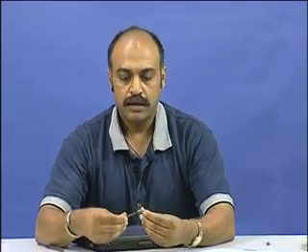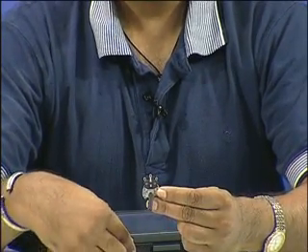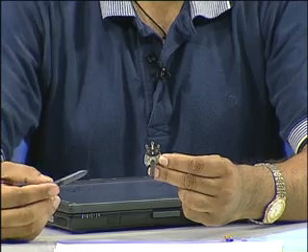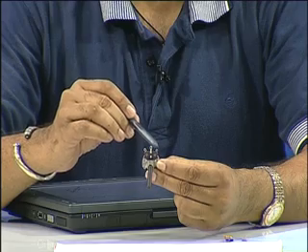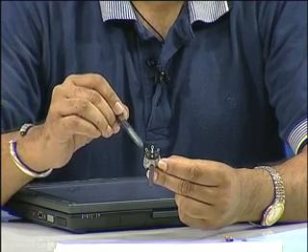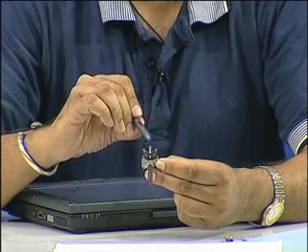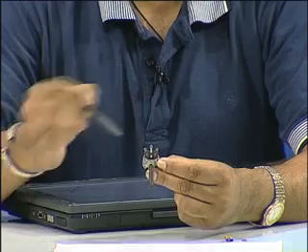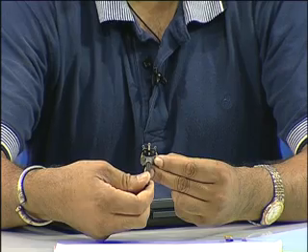Apart from these resistors, there are other resistors which are bigger in size to handle higher wattages. Now, here is one such component. This is also a potentiometer, similar to the low wattage blue box that you saw previously. This also has 3 terminals. These 2 are the extreme end terminals of the resistor, and this center terminal is the center tap, which will vary with respect to the end terminals, and the variation of the center tap can be attained by rotating this vertical knob which is around here.